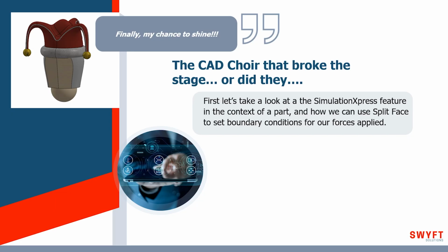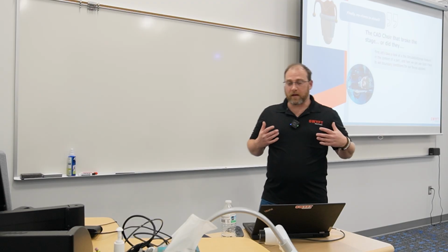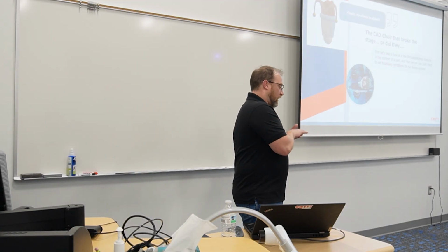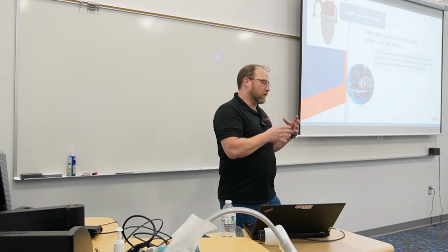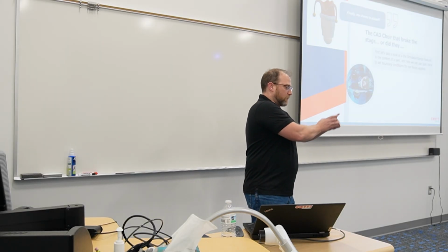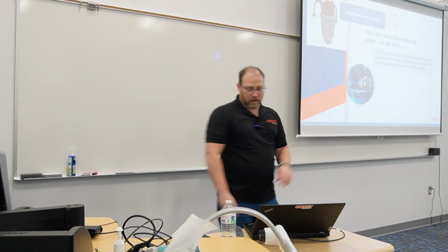We're going to start first with just a part, and in that part we're going to talk about the use of the split face feature in SolidWorks, and that will give us those boundary conditions for forces. You don't need to really have a huge background in engineering, but if you have a load that's spread out over an entire beam, you're going to have a different result than if you have a concentrated load in the center of a beam. We'll get into that here real quick.